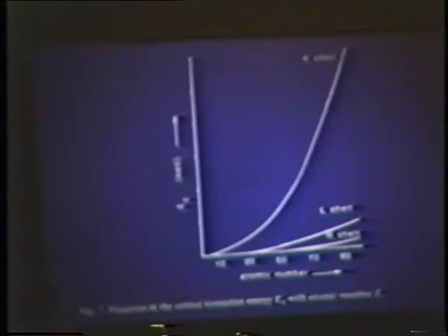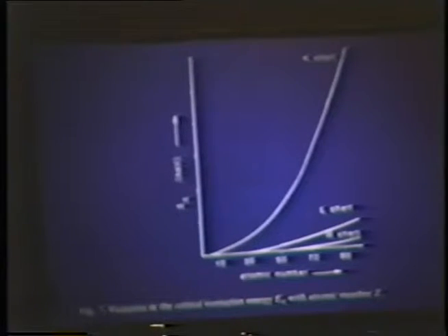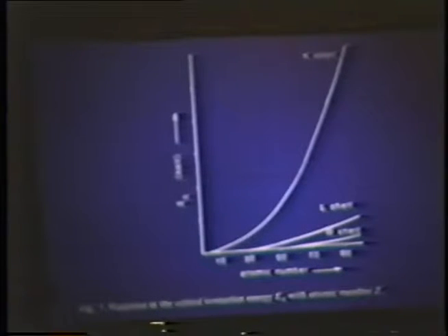Very low energy X-ray photons, i.e. something from lithium or beryllium, would be largely absorbed by the specimen. A few X-ray photons would escape from the light elements up to Z, atomic number 10, and many of these would be absorbed before they ever reached the detecting system. It is only when we get to such elements as sodium and above that there is a sufficient flux of emitted X-rays to make X-ray microanalysis a practical proposition.